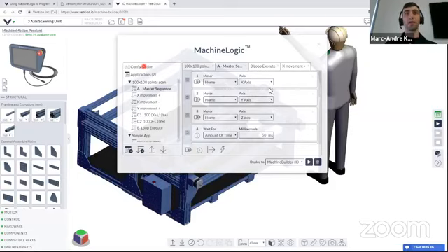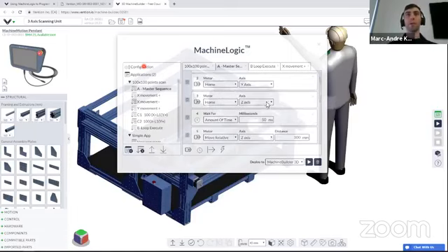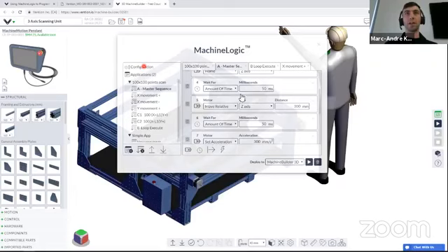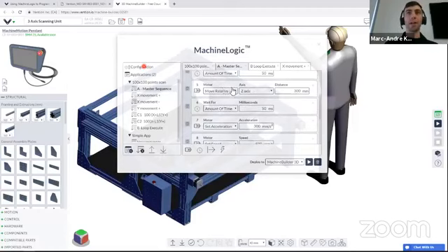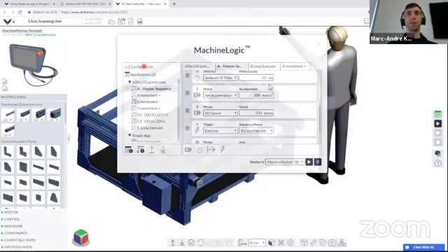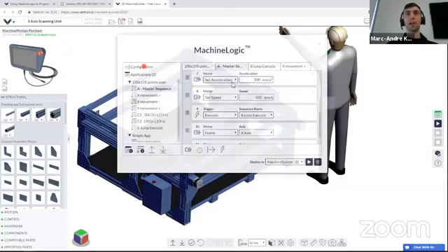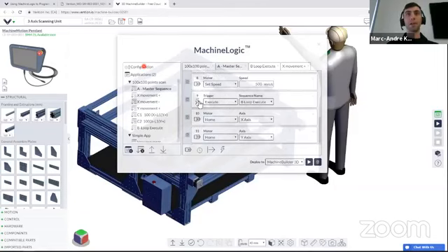You always need to home all of your axes first, so that you start from a repeatable point. Then you can add wait time if you need; if not, you can skip it. I made my z-axis move by 300 millimeters just to set it at the focal point. Then wait for 50 milliseconds, set my acceleration and speed, and then execute the B loop.